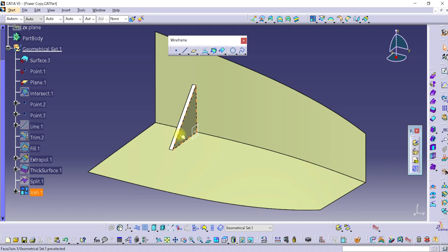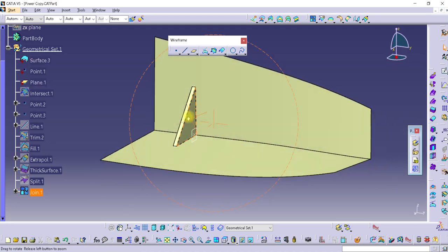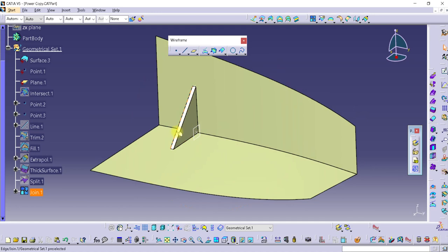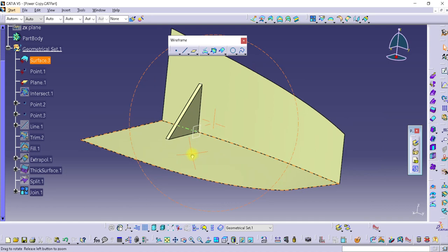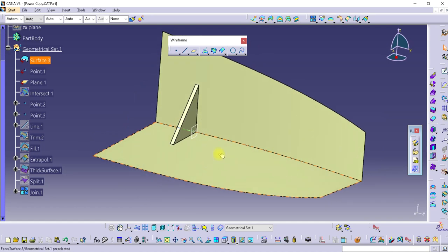After we finish our rib features, we need to test first, or we need to create the power copy. Then later if you really want to create a solid body, we can modify again. We test first whether it is robust enough to adapt to a different position.